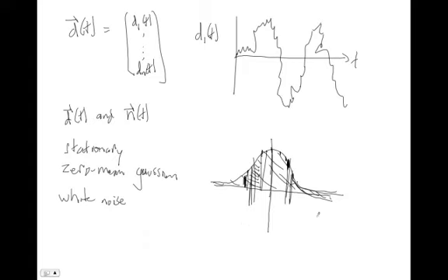So we're going to make this assumption about all of our noises, and it would be reasonable for a person to say, I don't know if my disturbances and my noises are like this. And so often what people do is they take noises and disturbances that they know for a fact are not zero mean stationary Gaussian white noise processes, and they model them that way anyway, because it turns out that the Kalman filter is fairly robust to these things.